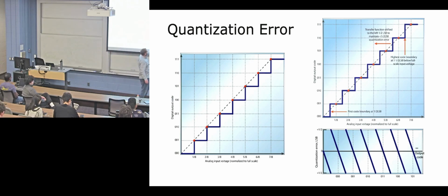And so here's an example of, from half a bit off, this should be minus, plus or minus half a bit of error based on how you set up your DAC or ADC. Could you minimize the quantization error if you increase the number of bits? Yeah, totally. You just pay the penalty of having more bits, more complexity. So that's one way to get around that.